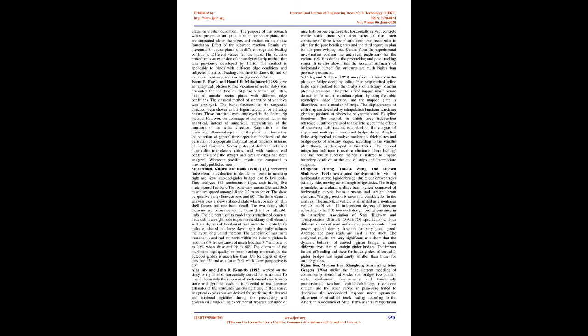In this study they concluded that large skew angle drastically reduces the design longitudinal moment. The reduction of maximum positive and negative moments in the interior girders is less than 6% for skewness of less than 30 degrees and as much as 29% when skew angle is 60 degrees. The reduction of the maximum positive or negative bending moments in the exterior girders is less than 10% for angles of skew less than 45 degrees and as much as 20% when skew angle is 60 degrees.